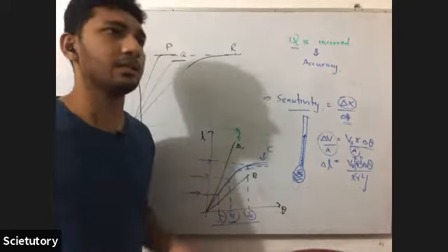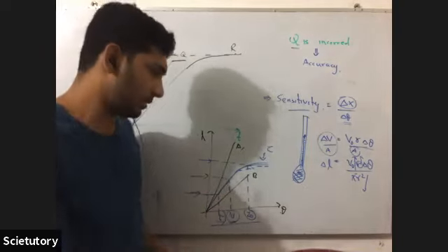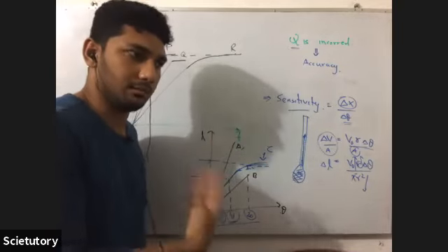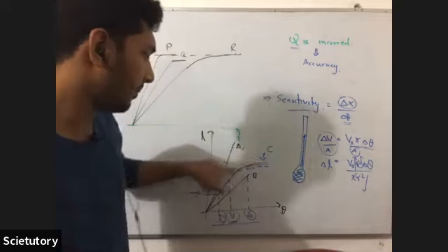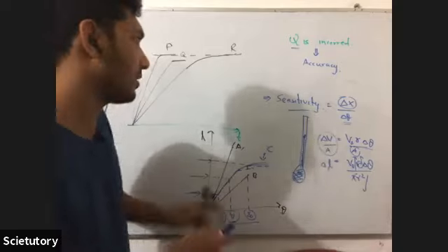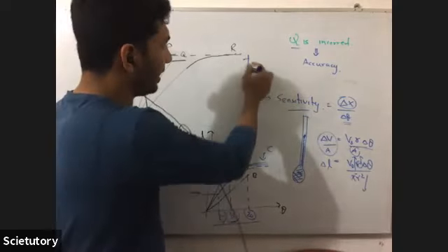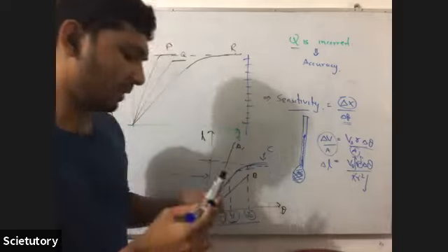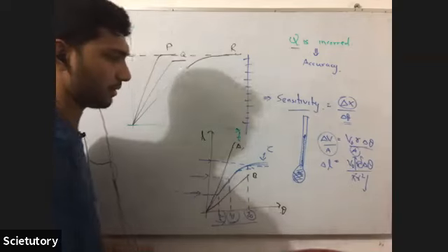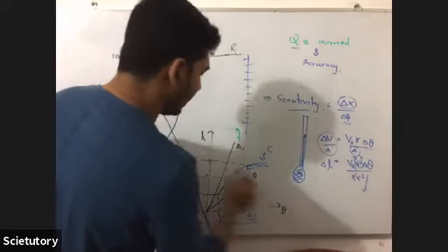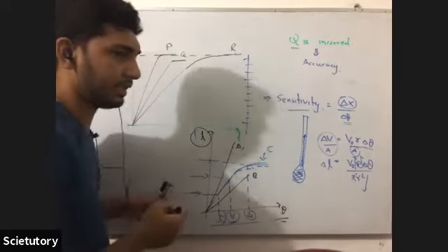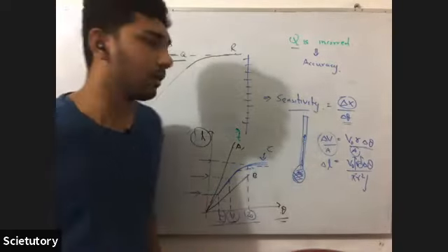So these thermometers need a graphical method. You should first graphically find the variation of length, and then you have to calibrate. You can't just find 2 points and divide the rest of the length into equal scales. You cannot do that. The graph should be for length with temperature to determine whether it has a linear or a non-linear scale. Not this graph.